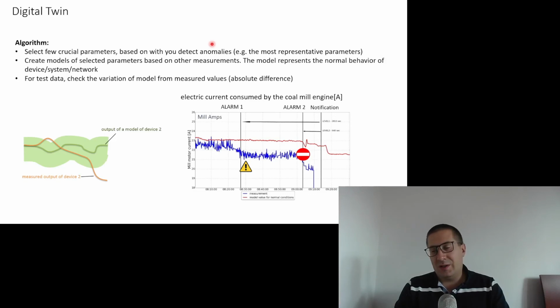As you remember, when I was also talking about the digital twin in this video at the beginning, we can take all the data that comes from the normal operation, and we can create a model of the normal process behavior, right? So let's say if we have 2 or 3 or 4 important parameters, important outputs of our process, we can try to model the values of those outputs based on process inputs. And then if we check that the model output differs from the real measurements, the estimated temperature on the outlet will differ from the measured temperature, then we can say it's an anomaly.